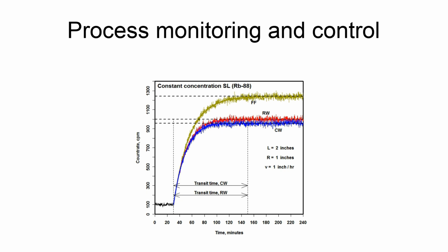Equipment at appropriate locations outside the control room shall be provided: 1. With a design capability for prompt hot shutdown of the reactor, including necessary instrumentation and controls to maintain the unit in a safe condition during hot shutdown, and 2. With a potential capability for subsequent cold shutdown of the reactor through the use of suitable procedures. This defines a requirement for monitoring the air intake for the control room, such that the exposure limits, including for inhalation exposure, shall not be exceeded. CPAMs are often used for this.